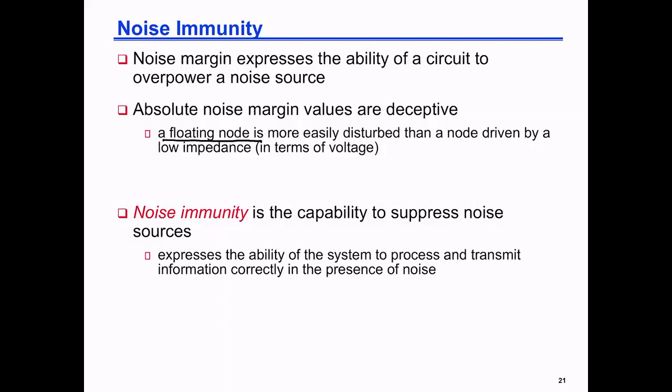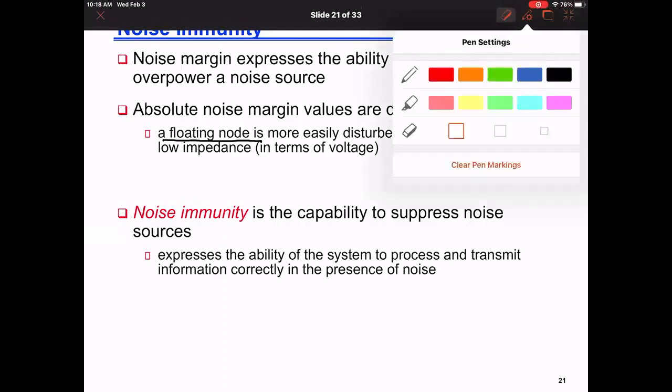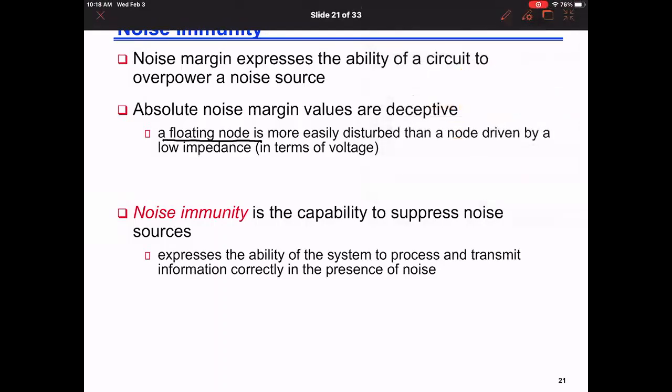Okay, we'll explain them later, but let me give you a high-level example, and later we will see it in real practice. Let us assume that I have a line, and I typically pre-charge it to VDD. So I'm pulling it with a PMOS, and then I turn this PMOS off. So the signal is low then high, right?